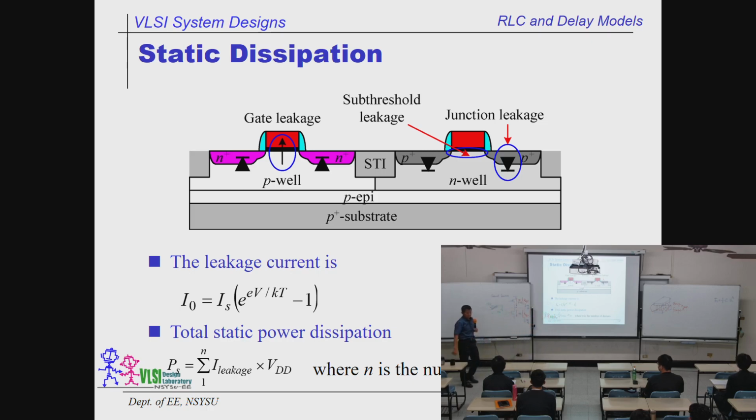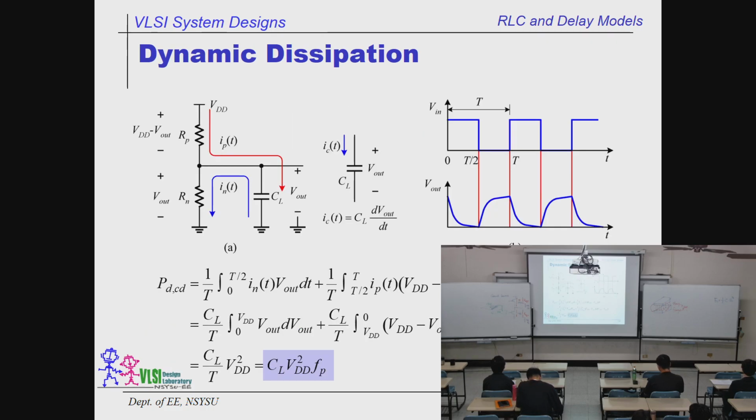So anyway, this is static dissipation. All right? So now this gives you the conclusion that I just said. So this is charging and discharging. The square wave on the top is the input, and the ugly wave generated from V out looks like this. If they are the equal size, see that? So the charging is slower, discharging is faster, something like that.